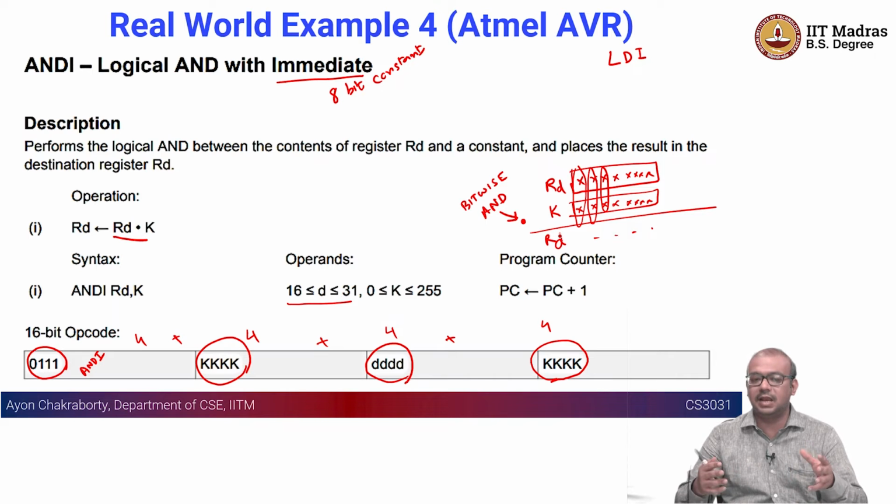Other than the scale, there is a lot of thought process that has gone into designing the ISA. We are not putting much thought into coming up with the ISA in a very systematic way or in a tricky way to optimize something. We are just saying 4 bits for the opcode, or the operation, and 4 bits for the operands, and you can support this many instructions.